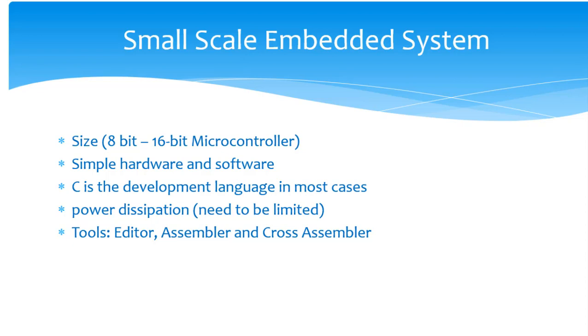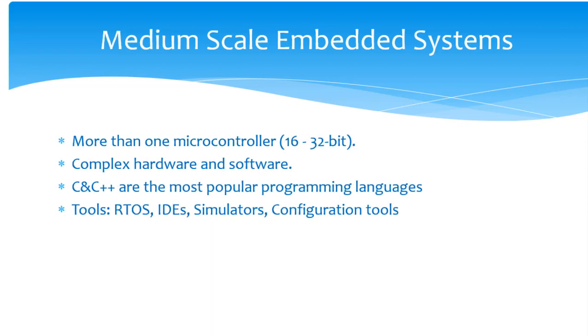In the medium scale embedded system, you will find more than one microcontroller, 16 or 32-bit microcontrollers. It has complex hardware and software. C and C++ are the most popular programming languages for developing medium-scale embedded system. The tools here are RTOS, IDEs, simulators, and configuration tools.